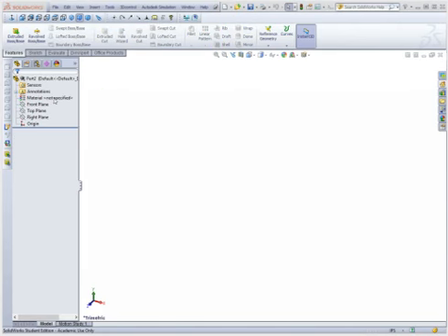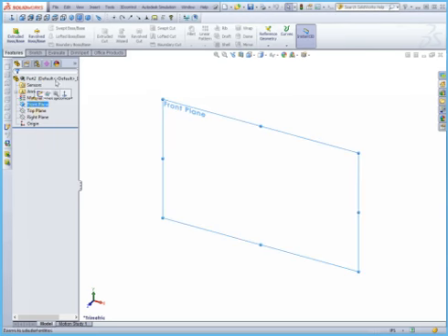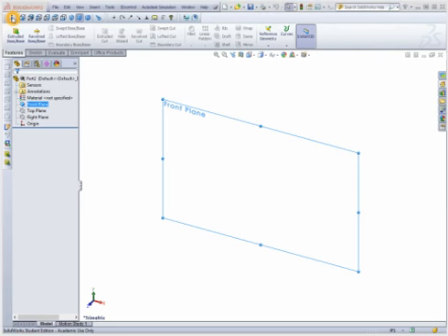So we're going to draw the smallest circle that we need to represent this gear and add the actual teeth on top of that. So doing so, we're going to be drawing the actual addendum circle first and then adding teeth on top of that. Before we can draw the addendum circle, we need to actually determine the size of the gear that we want to draw. In this case, it's going to be an 18-tooth gear with a diametric pitch of 2 teeth per inch.